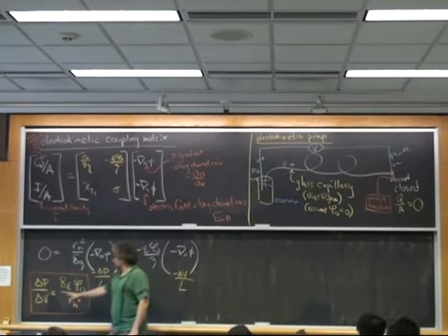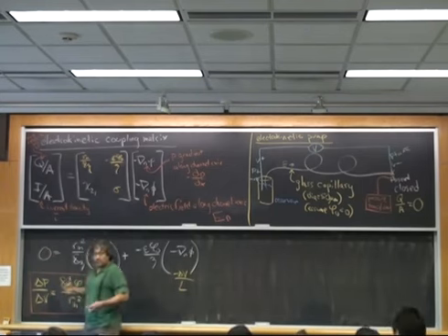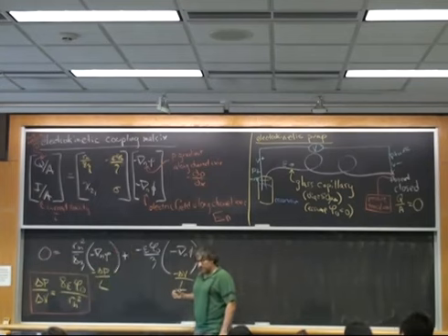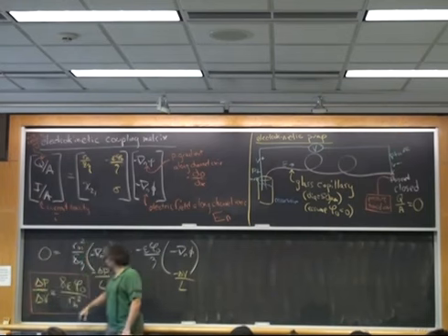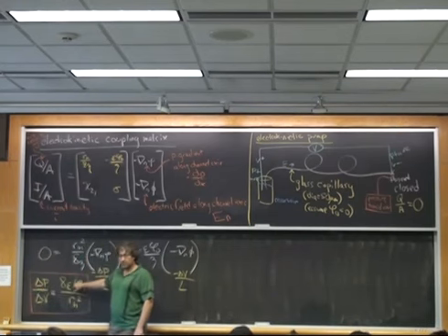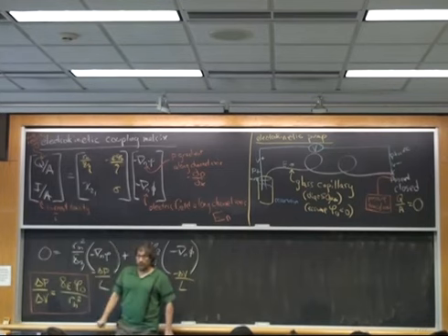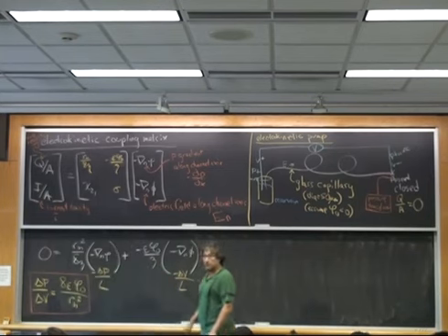The electrical permittivity is here, because if I have a material with a very low permittivity, the real force I have to put into the system to get a voltage isn't very high. But with something like water, I have to put a really big force into the system to get that electric field to be of a specific magnitude to get this voltage, right? So an electrokinetic pump that I run with water is going to be 40 times more effective than one I run with dodecane or something like that.